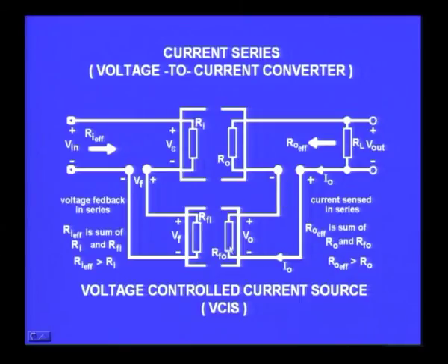Now it is R0 plus RF0, and therefore the effect is to increase the output resistance from this side, and the effect of giving a voltage in series with the input is basically again to increase the input resistance. So the input resistance is also increased, the output resistance is also increased by this feedback configuration.